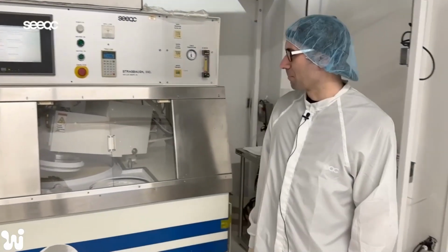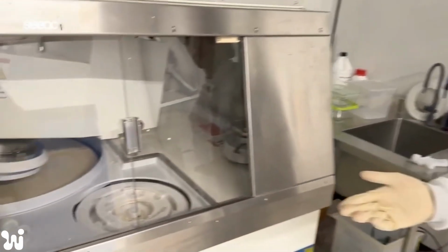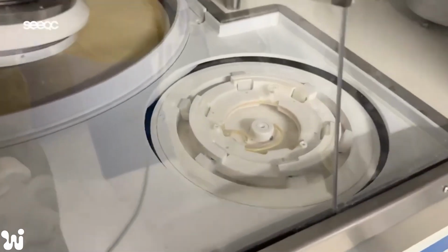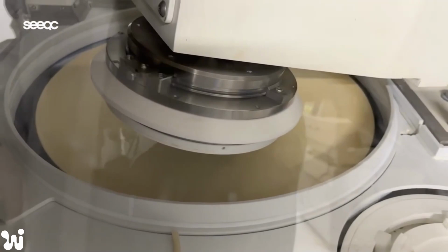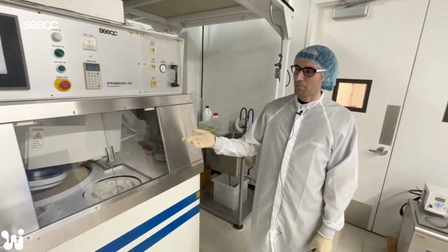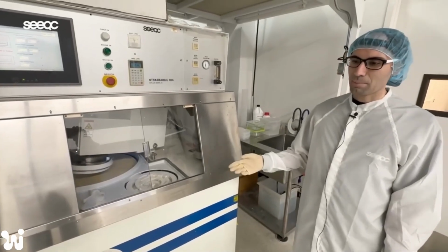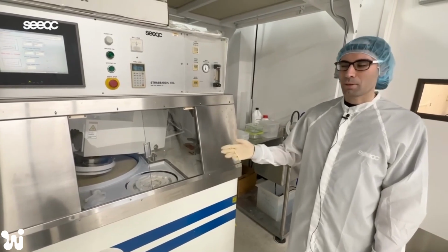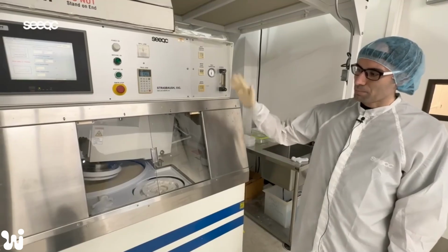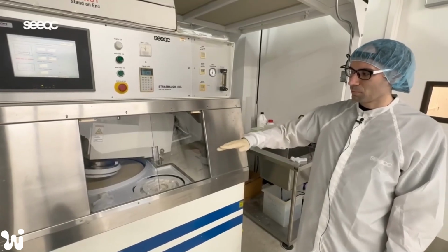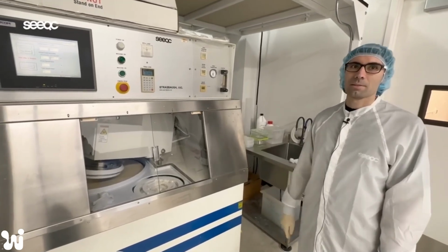So here is a chemical mechanical polishing machine, and what it does is it smoothens and flattens a layer of our wafers so that we could add more complexity to our chips. A wafer is held by vacuum by that polishing head there, and a slurry, which is a chemical mixture dispersed with nanoparticles, is put onto that pad there, and the polishing head applies mechanical force combined with that slurry to smoothen out and flatten that surface.